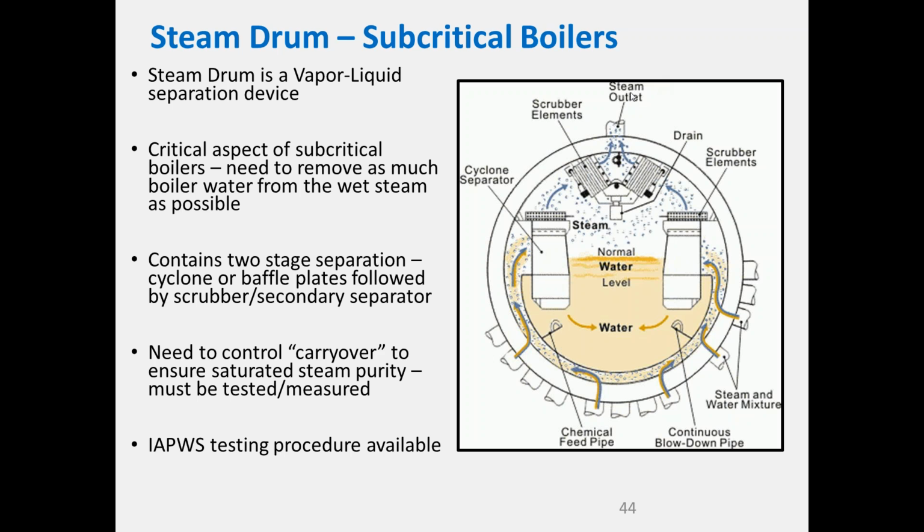And what you need to do here is you should be doing periodic, what we call carryover tests. If you go to that IAPS website, there's actually a test protocol available, and what you do is you measure sodium in the steam versus sodium in the boiler water, and you can calculate the ratio of carryover and determine whether you have a problem or not at your operating pressures.